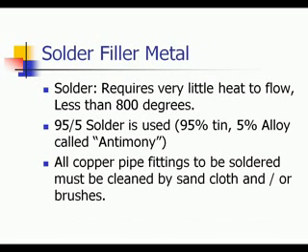This is an example of the oxy-acetylene torch. The acetylene is on the right, the oxygen tank is on the left. They get very, very hot, and you can actually burn through pipe and metal if they're not adjusted properly.